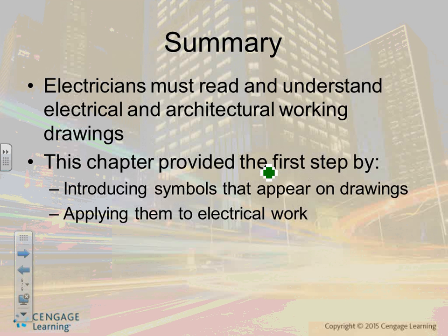3 pole, double throw. That's the auto transfer switch, they call it. When you have an auto transfer switch, you have 3 pole, and you drop each one of them to one side or the other side. So the poles and the throw. Yes, 3 on the one, 6 on the other side. Why 6? Because 3 coming from the normal and 3 coming from the emergency. Anyway, it gets interesting. So these are all your switches, gentlemen.